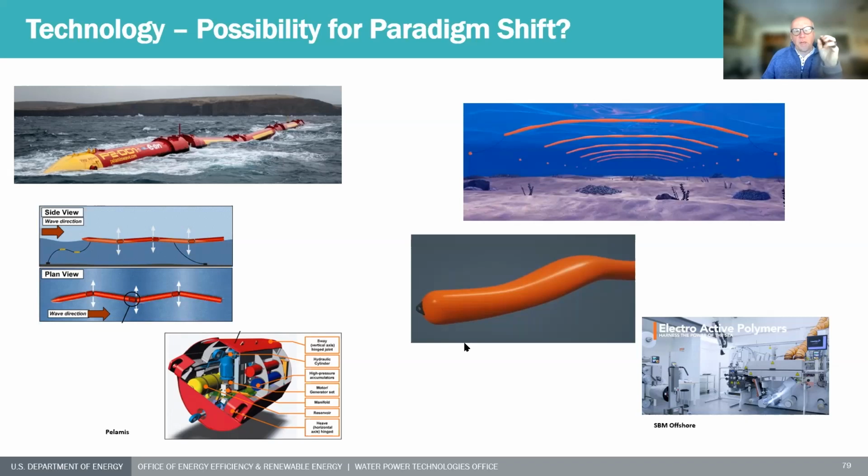The guide vanes themselves, of course, would ideally look different in the different flow directions. Like you have pitch control, you would like to control guide vanes, and there are passively controlled guide vanes as well, which flap open and close or have two end stop situations. And that of course gets complex in manufacturing and reliability. We developed a bidirectional impeller design. Interesting, show us. Have you heard of any work in this area using a bidirectional impeller?